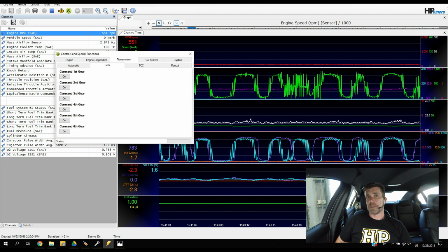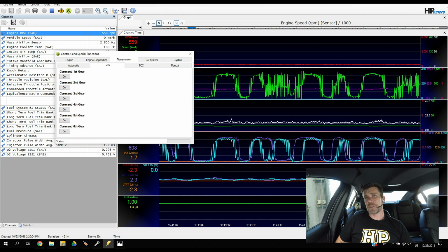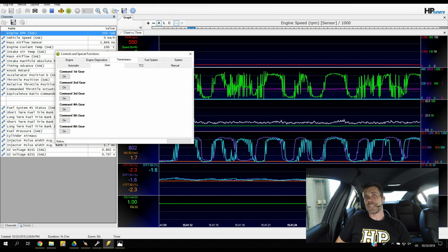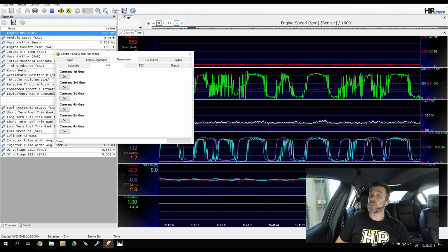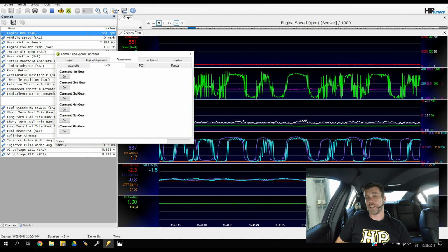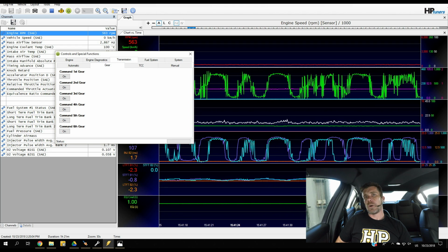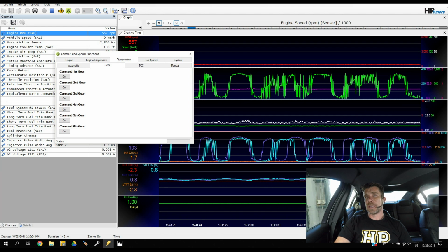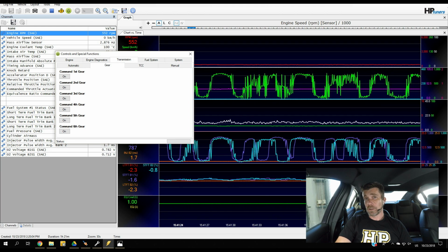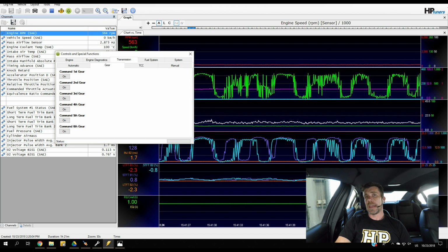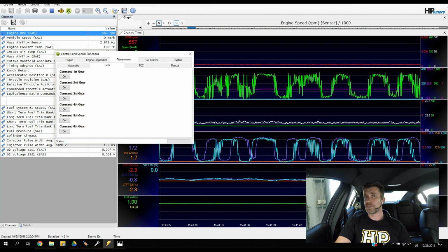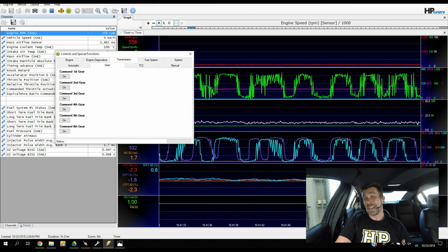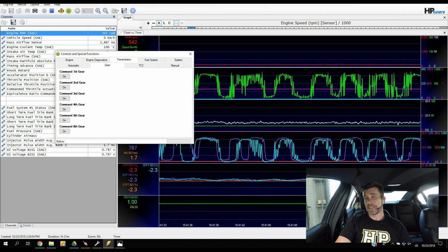The other option is on some of the earlier 4-speed automatic transmissions. These were a little bit less sophisticated, and these do tend to kick down regardless of whether you try using the scanner to lock the transmission in a specific gear. What I did with this, and I'll just share this little tip, is that I'd run those particular engines in 3rd gear on the dyno, and you'll find that if you're trying to settle at around about 2000 or 1800 RPM at the start of a run, if you go all the way through to full throttle, it will kick down into 2nd gear, and it's going to ruin your day.